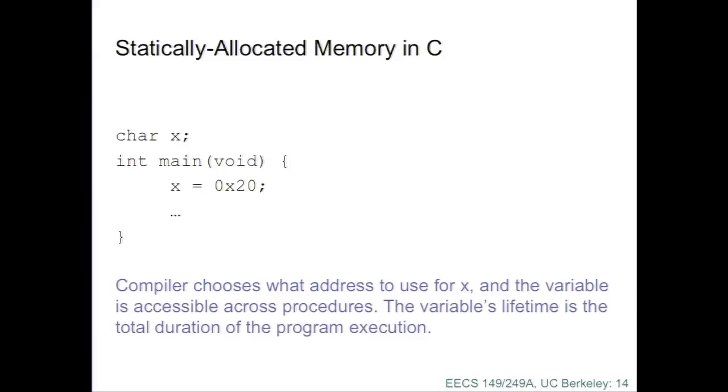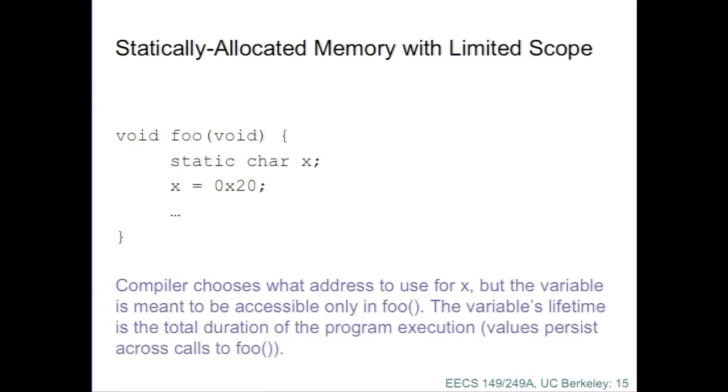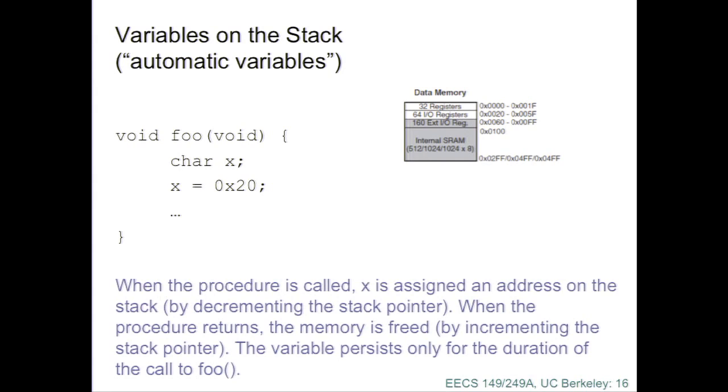Now what that means is that if you load your program into memory, and then you push the reset button to restart the program, it doesn't reinitialize the variable. That memory location will still have whatever the previous execution of the program had. That's a very interesting source of bugs. It means that when you push the reset button on your processor, it doesn't necessarily go to the same state it went to when you loaded the memory. Very tricky.